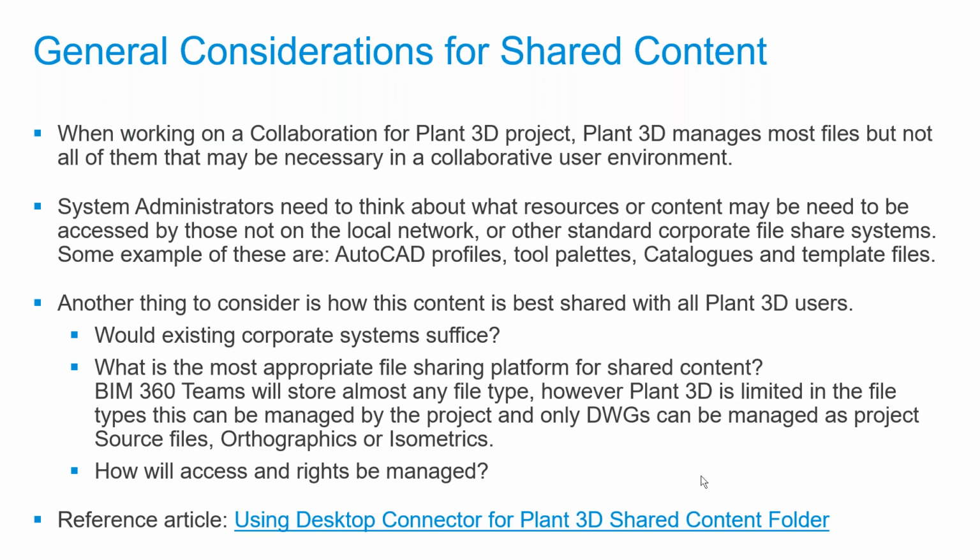We've been looking at ways to perhaps manually copy those or upload those to BIM 360 Docs and then use desktop connector. We've had some success with that. The main limitation we found is that the individual users have to go in and download that catalog when there's changes. It doesn't automatically cache it down. In other words, if they were to go into Plant and open a spec, it doesn't really see that there's new catalog content to automatically pull that down. So that's something we're working on with the product teams, putting those in as user stories to see if we can get something around that.